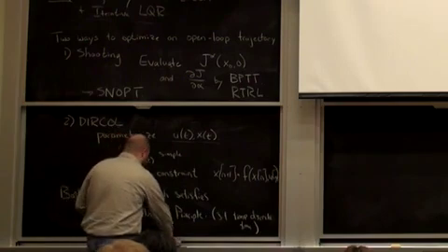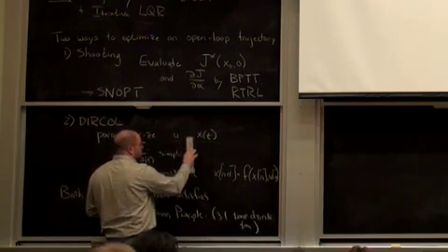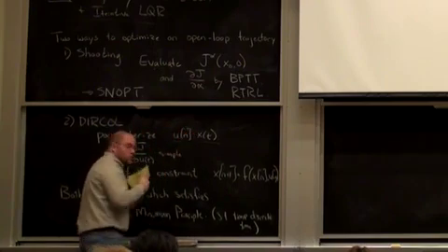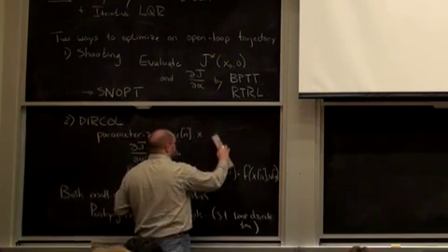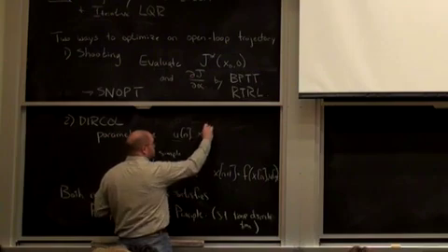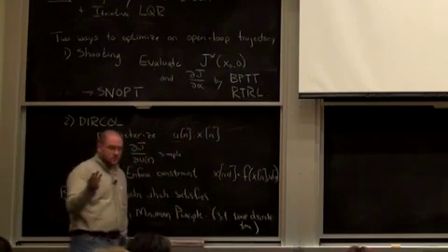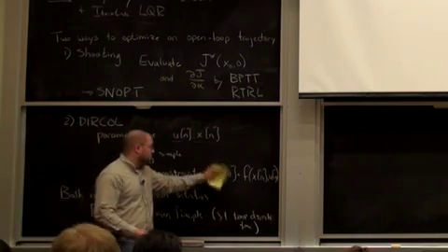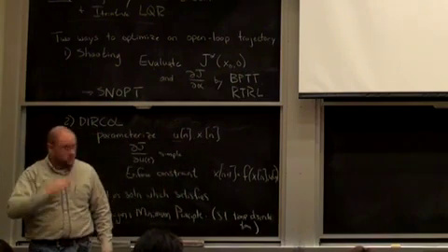So in fact, the parameters that you hand in, maybe it's easier to think of it as a discrete function of time, because you're going to hand it u at certain points in time, and you're going to handle x at certain points in time, right? And this discrete time update can be an Euler integration or a higher order integration of your continuous dynamics, but you only satisfy the constraints at discrete intervals of time.